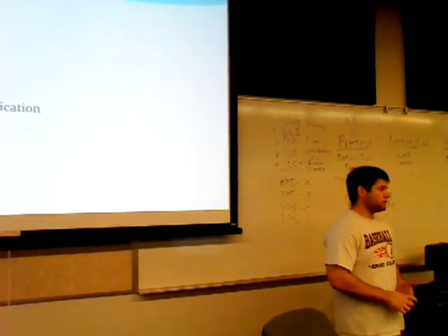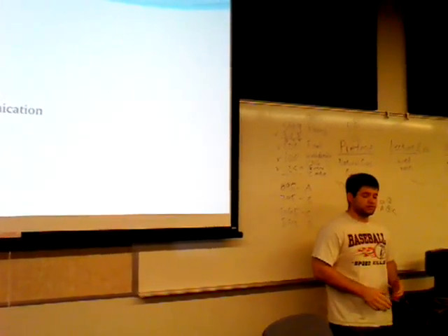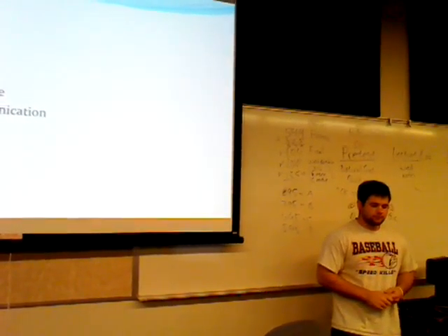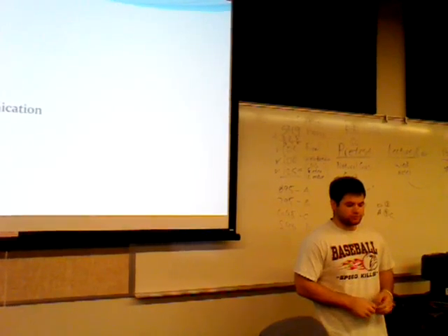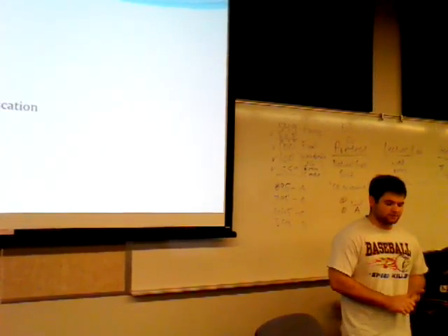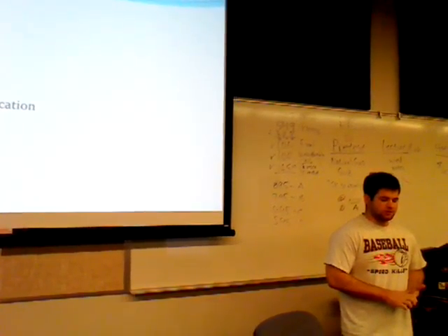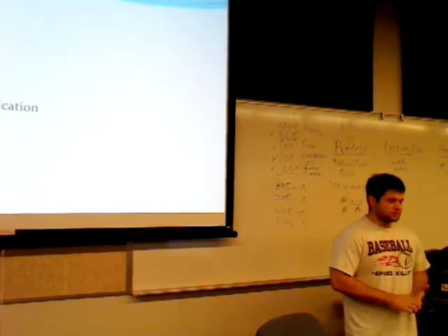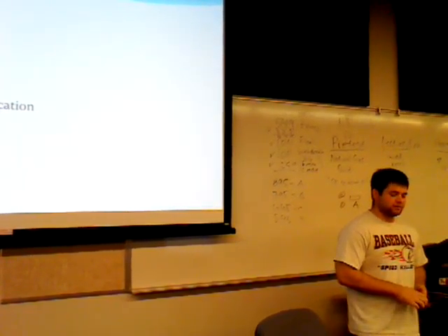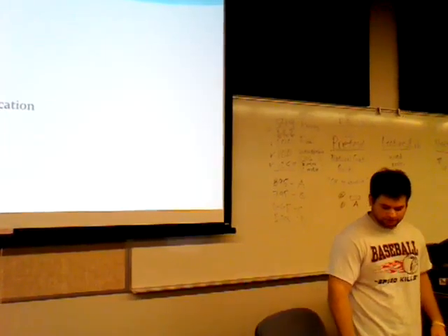The high and low thresholds are important, so I can set the tolerance that I want the temperature to be at. And the output resolution is basically how many bits I can have it send. And the input-output serial communication is going to be used through the SPI port, which I can use to set the PMOD, and I can receive the data.